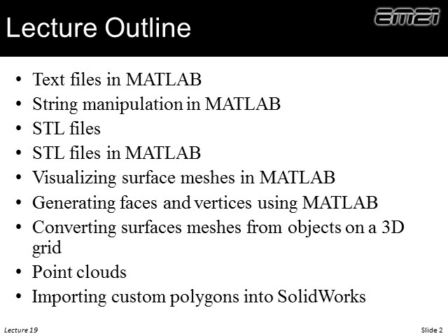for describing 3D objects in 3D printing. It's a limited file format, and it will change, I think, over the coming years, but right now that's the standard for exchanging 3D geometries and driving 3D printers. So what we want to talk about is STL files in general, and then how do we read and create STL files from MATLAB. I'm going to talk you through creating ASCII STL files, text STL files. They become very large for complex objects. A binary STL file is much more compact and not a whole lot different than what we're talking about here, but I didn't want to get into the binary commands from MATLAB. So a text file STL is just fine for this lecture.